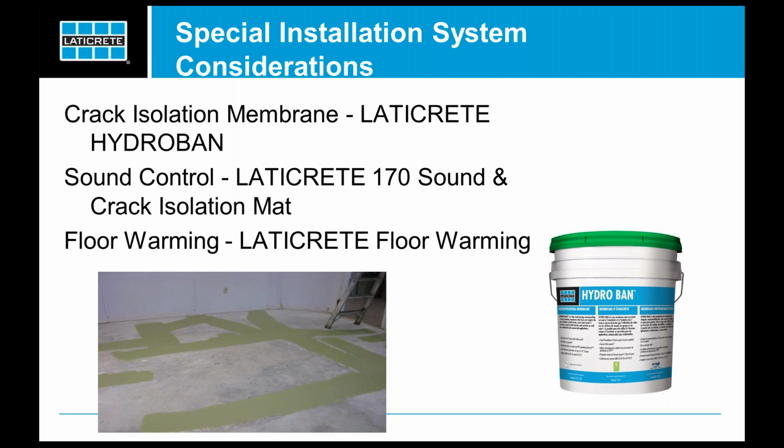So now we've got our surface preparation all in order. We're nice and level, we're flat, and we're smooth. And now you might want to start thinking about what other types of materials may be used in an application. Is it a wet area? Does that require waterproofing? Is the finish potentially prone to cracking, or might there be some cracks in the substrate as well? Does a crack isolation membrane make sense for the application? Is sound control needed, whether it's regulated by code or by city ordinance? And even floor warming can also be considered.